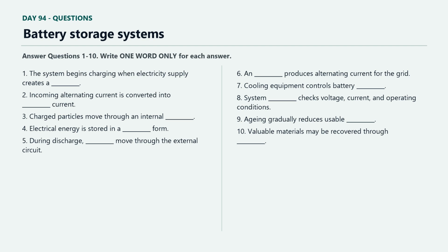Stored energy is not simply electricity waiting unchanged inside a container. Charging alters the chemical state of the electrodes. The reaction cannot proceed without limits. Excessive voltage can damage materials, while a very high charging rate can produce unwanted deposits and additional heat. Cells are therefore grouped into modules and larger packs with electrical and mechanical protection.